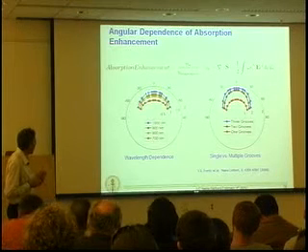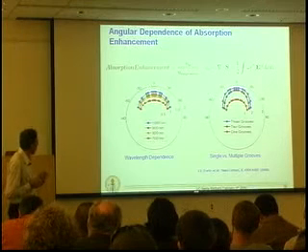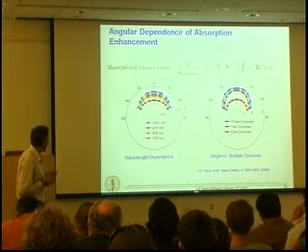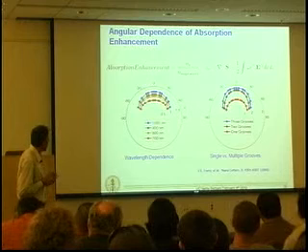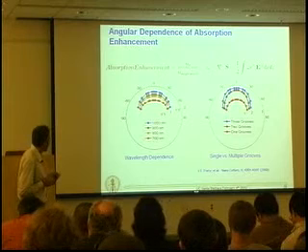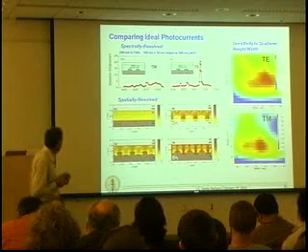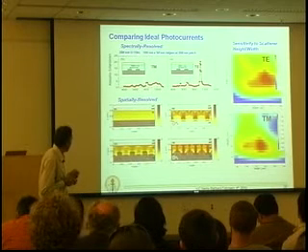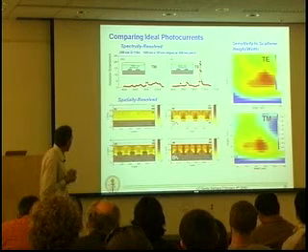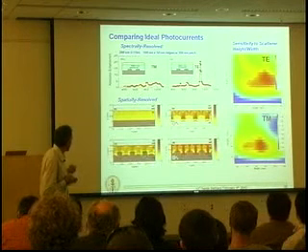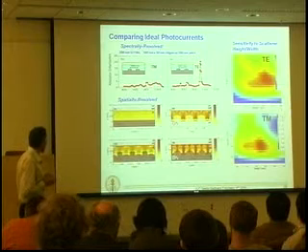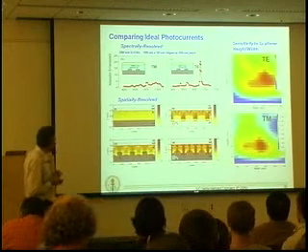And this shows the relative angle independence here of the absorption with just, for example, a single scatterer or an array of scatterers. So indeed, these sub-wavelength scatterers do have the property that they have broad angular acceptance. So then the next thing that we do is to look at the different modes, and different modes have different spectral absorption. And we're interested then in determining what, of all of the modes that are excited in this thin film of semiconductor, what combination of modes and combination of coupling into modes gives rise to the largest photocurrent.